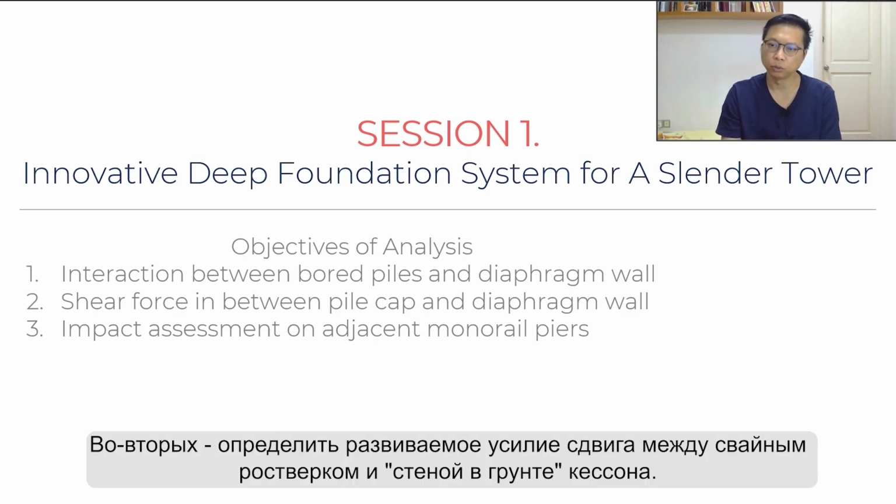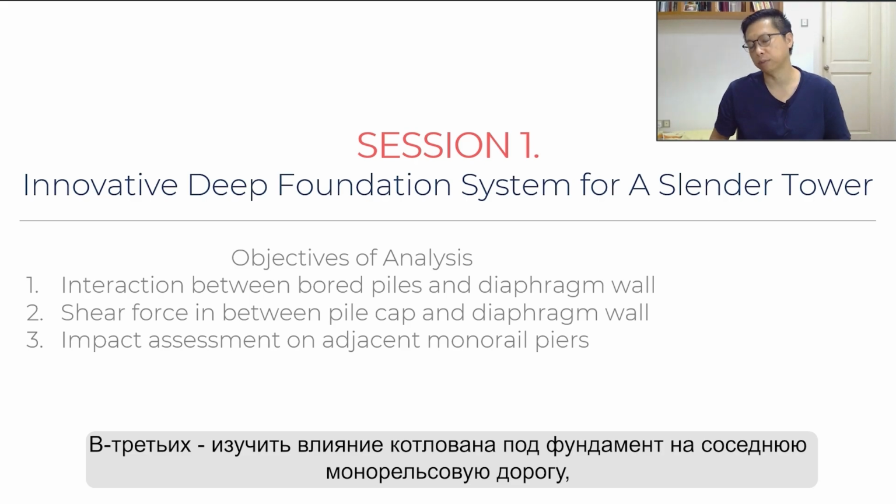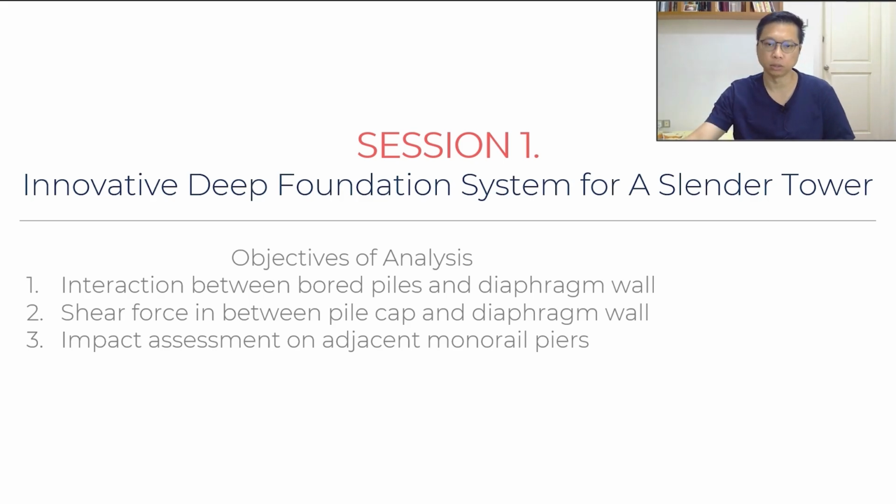Number 2, to determine the forces in the pile cap and the diaphragm wall coffer. Number 3 is to study the impact of basement excavation on the adjacent monorail piers. So we can simulate the problem in one three-dimensional finite element model.